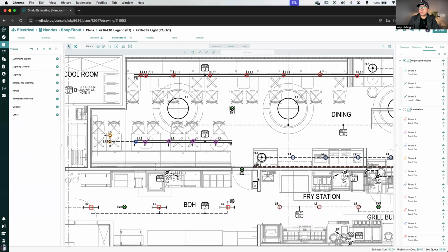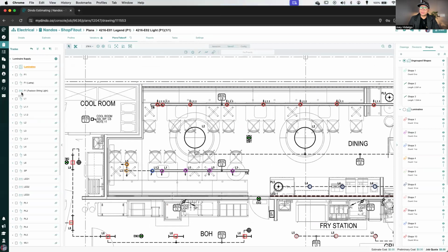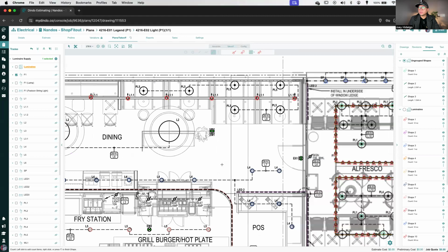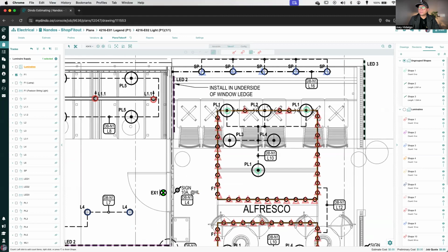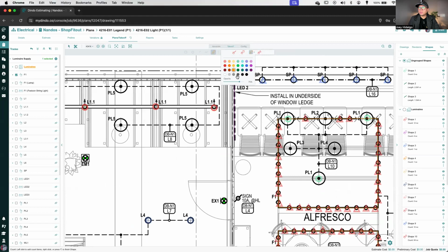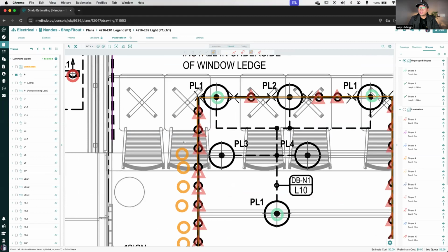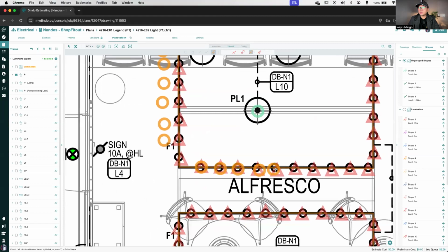Again, like I said, this is a quick demo. If I'm going to count the lights, all I need to do is expand this bit and then select that item. Then choose the symbol that you want, one you can easily identify. For that one, I already used triangles, but just for this demo, I'll show you that you can use another symbol. For example, there, so you can start counting them up. Although I put in some already, you can also go on top of it. Let's say you want to change it.